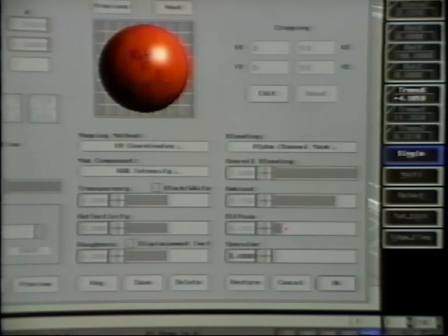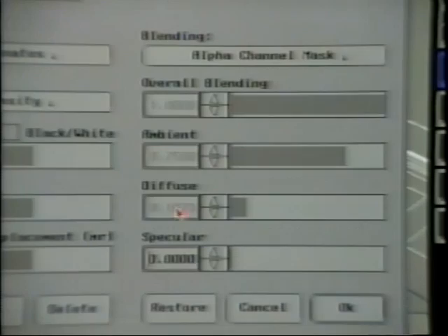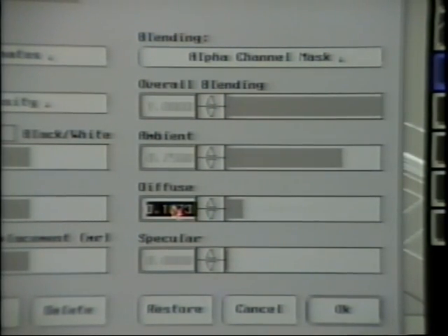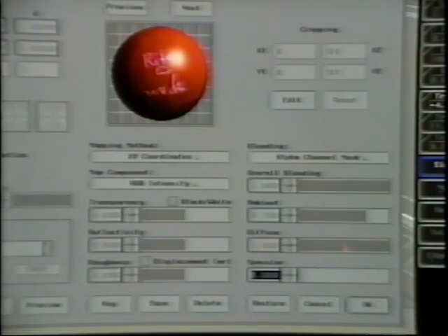We can even type in a brightness value outside the slider range to texture on a diffuse color brighter than the colors in the map. Or we could adjust it darker for more contrast, which is what we want here. We're still seeing the specular color set in the original material, but setting the specular slider to any non-zero value will replace the material specular color with the color from our map.